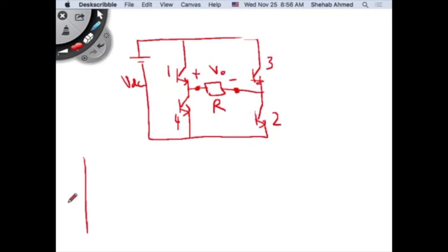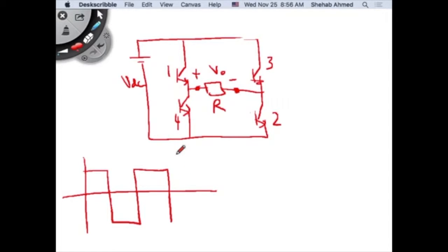And that's what you're building. You're building that after the 12-volt battery charger, right? You're building a high-frequency AC converter. That's what you're doing, right? This is AC, this is not DC, right? Why are you doing that? You're doing that because you want to boost the voltage. You want to use a transformer because you want to boost the voltage from 12 volts to 180 volts.